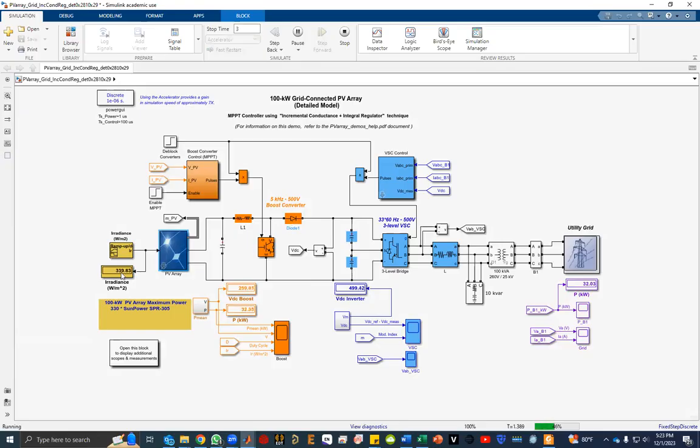See, the irradiance is changing, and with it the voltage is also changing, but we cannot have fluctuating voltage in our system, right? That's why we need a boost circuit. So this is the boost circuit, and after that it will give you 500 volts fixed voltage.